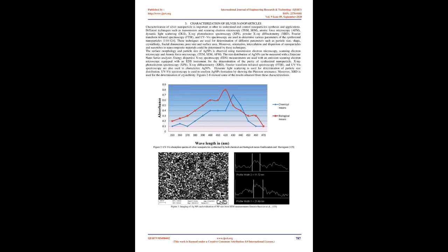Electric discharge method. In this method, pulse voltage is applied between an electrode and a workpiece that are kept close to each other. Dielectric breakdown takes place at a certain distance between the workpiece and electrode, which causes high heating of the workpiece to melt away a small amount. The excess workpiece material is removed with the help of a steady flow of the dielectric fluid and also cooling in the machining. If current flows through a workpiece, even a hard metal can be machined.